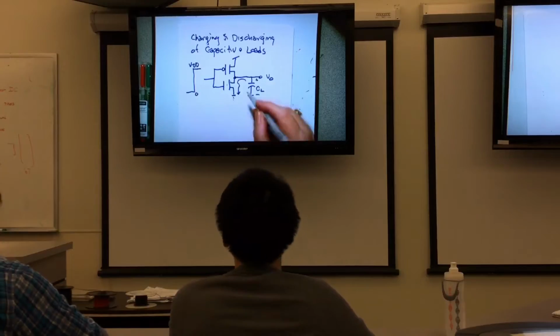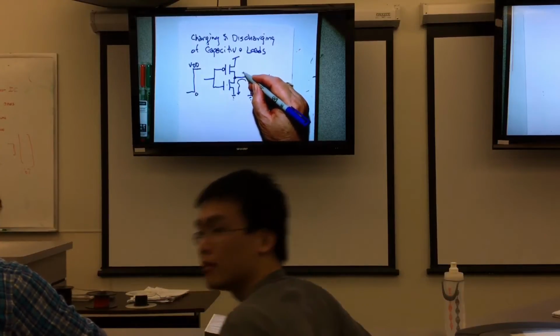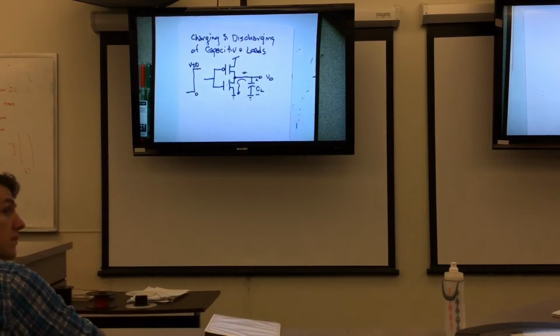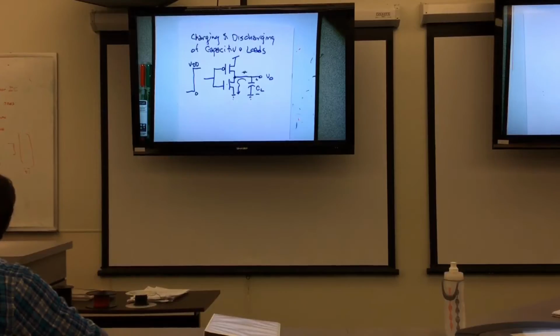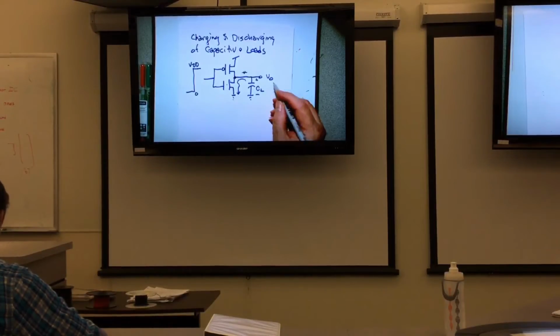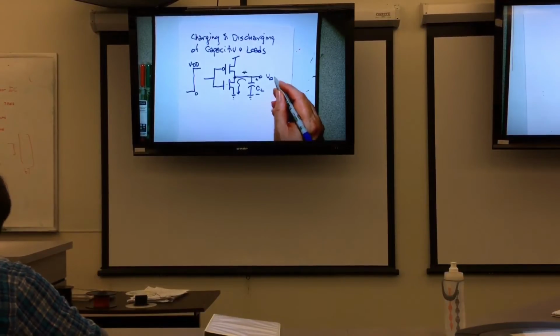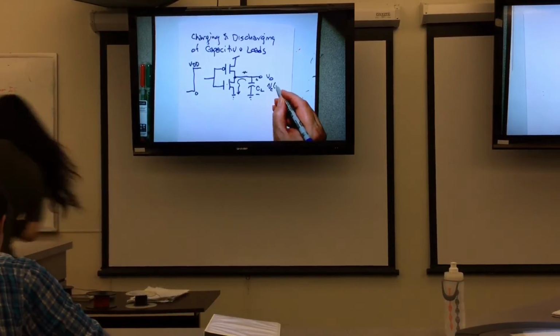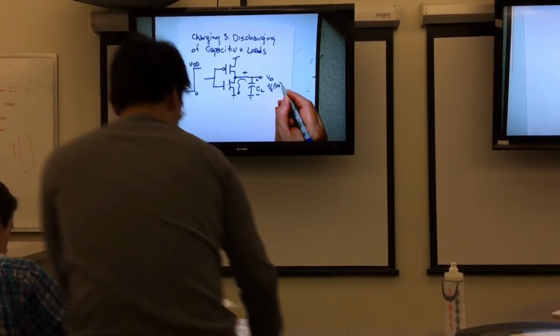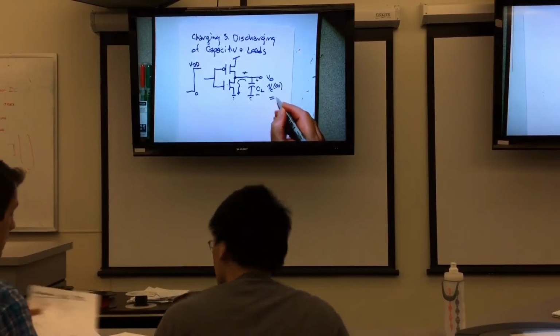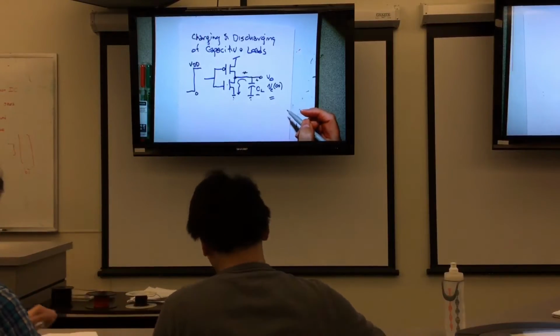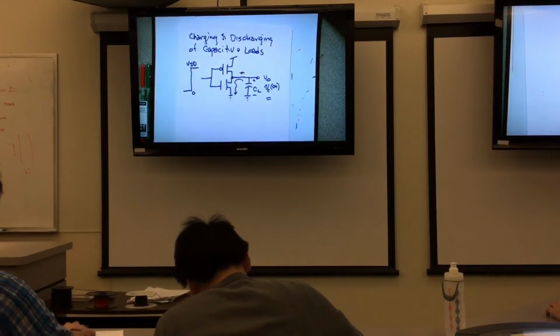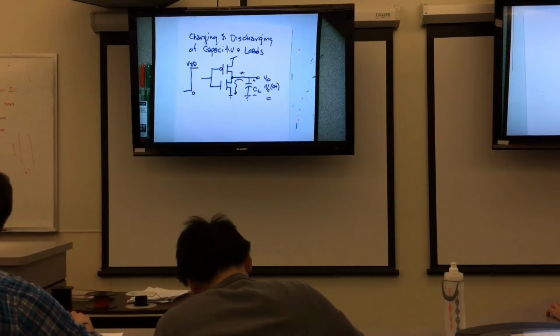In the process of doing it, there's a little sneaky guy that's starting to show up here in the wire. A resistor here. We're going to ignore that resistance in this calculation. So the C cell has an initial voltage V out, which we call VC, which is initially going to be maybe VDD, or possibly not fully VDD, even though we're assuming it is VDD, and it will be really nice if that's VDD.